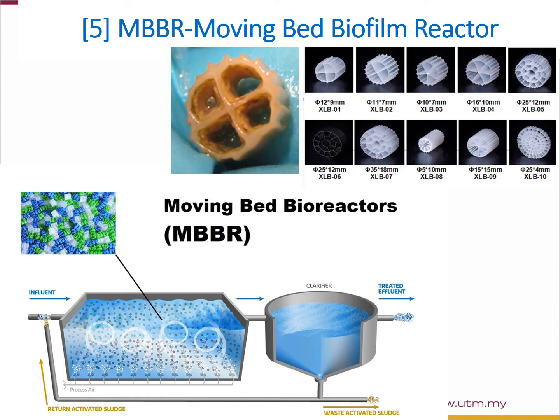And all this will be floating using some compressed air, sparging through the bottom, will float all these carriers and actively attach a lot of the biomass after degrading the pollutant, so that the water coming out from this moving bed bioreactor will be substantially clarified.